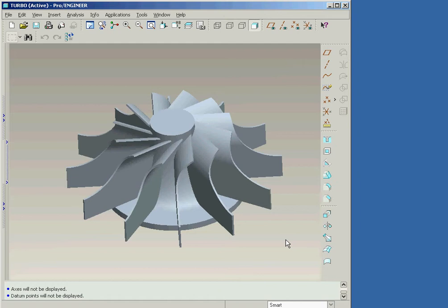In this session, we'll illustrate how to create a radial pattern that is based on a sketched feature. During the creation of the pattern leader feature, we'll use the make datum operation in order to create an angular dimension that will then be incremented to produce the pattern.